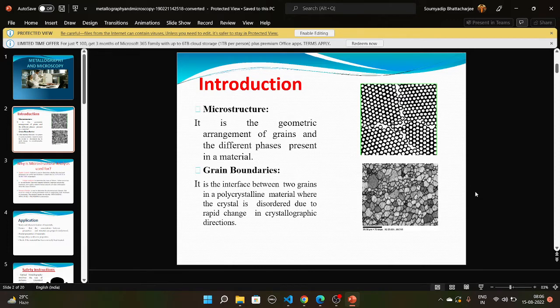Yes, sir. Now, why I'm referring to this case especially: that machining is what is called conventional machining, not unconventional machining. In conventional machining, the requirement is that the cutting tool should be harder than the job material, because while you start machining, the cutting tool will indent into the job. It will give some depth of cut, and you have to go for some feed, some cutting speed, etc. These terms are there probably in your machine technology subject. The requirement is that the tool material should be harder than the job material. Otherwise, you cannot machine your object.